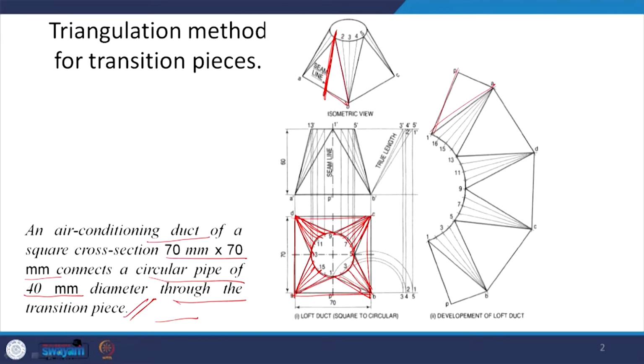Now, this is slant. So, you have to determine the true shape of this triangle, which is how they have taken the true length. What we are doing here is very simply taking the radial base and then projecting it above to get the true length. Or what you could also do is project and make an auxiliary plane parallel to this face to get the actual shape of the triangle. So, either way, whether you arrive at the true length by taking the radial length and projecting it along the same height, or you take it on an auxiliary plane, either way is a correct method. So, we draw half of this triangle here.